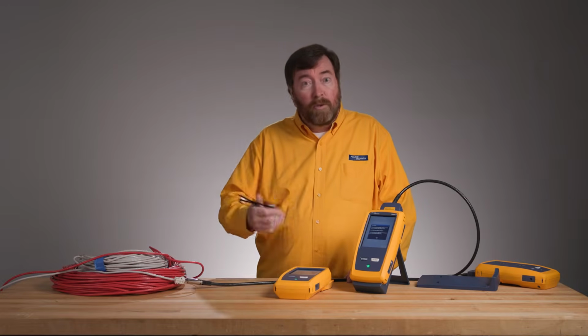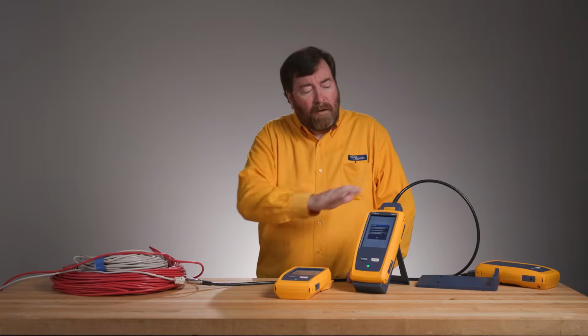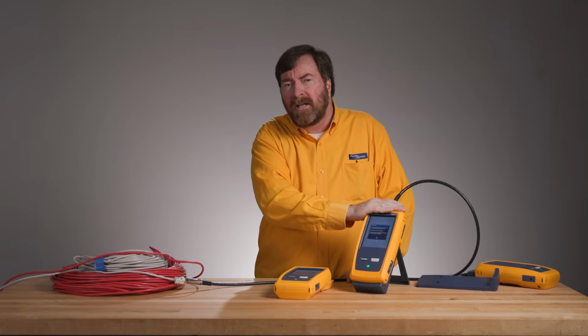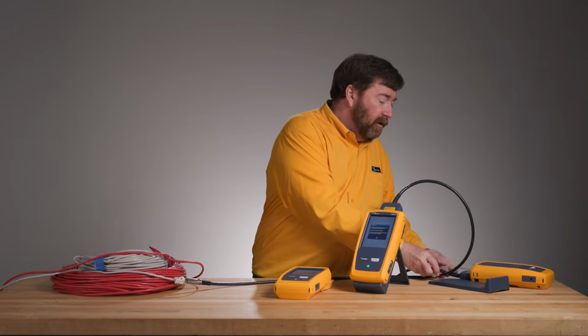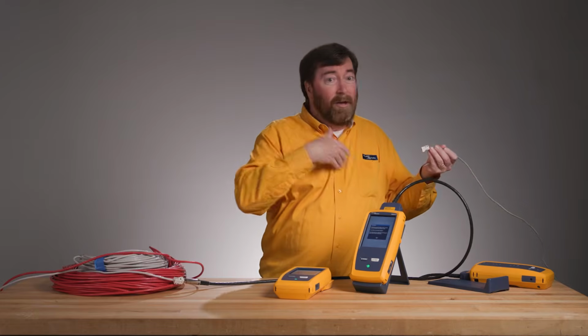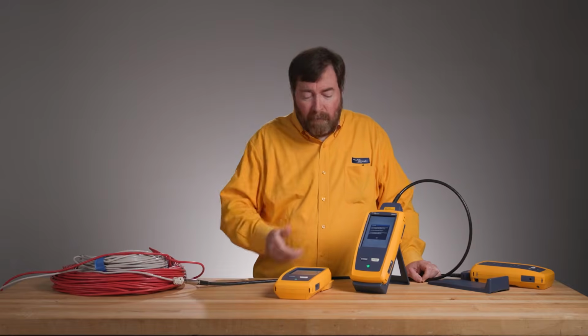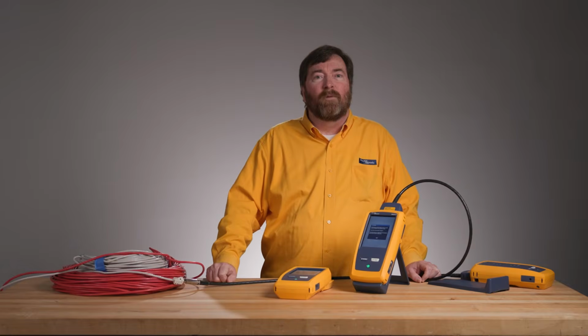Okay, we've covered a bunch of subjects here. The new TIA 568.2-E revision of the standard now defines values for loop resistance and resistance unbalance, and we've seen how we've put the new default test limit in the tester, our plus PoE values. We saw, and frankly, this cable scares me, this copper-coated aluminum cable passed the standard category 5E test limits. It was only by using the plus PoE values that we saw that it has too much resistance. PoE isn't going to run as efficiently on that. We saw our extended reach limits from many different manufacturers, and we saw this useful warning message that the calibration is expiring.